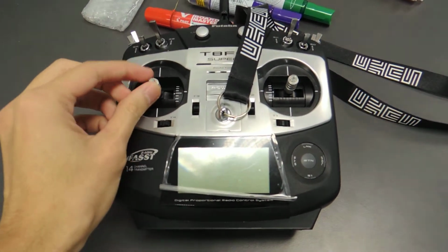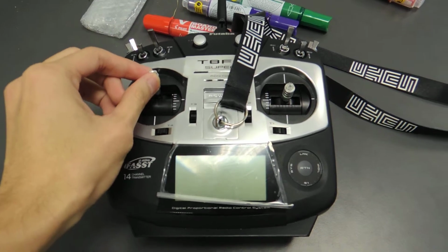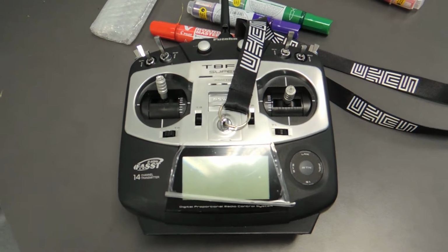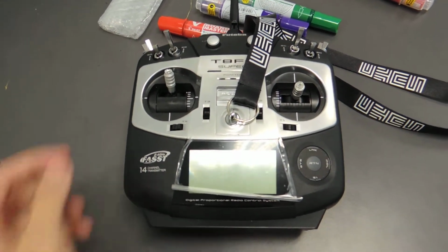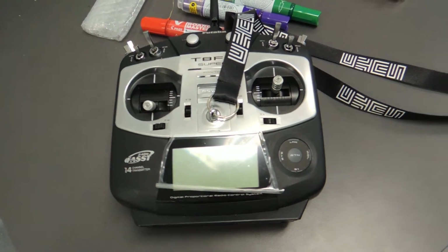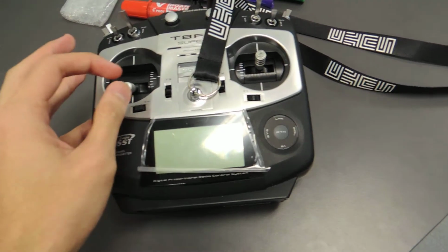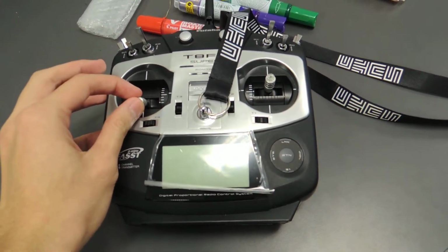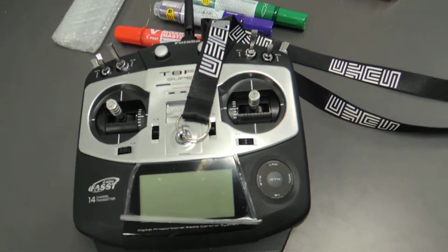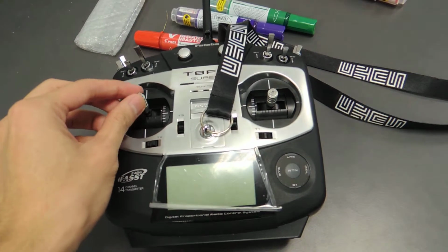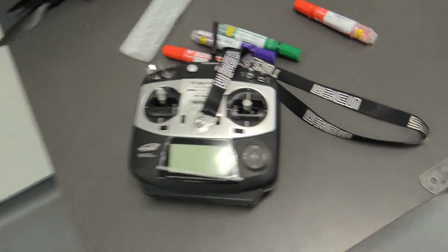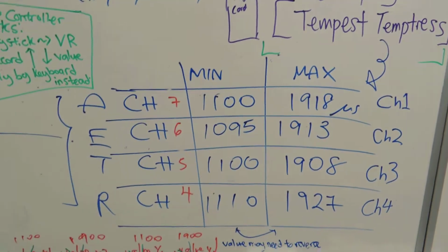When you are powering up using a controller, for example, you are giving a signal of sending full throttle. It gives a certain value to the flight controller on board. And when you are pushing it down all the way, you give another signal of a different value. That's what happens when you are trying to control a flight machine, for example, a quad-rotor. And if I were to power it to an intermediate step, it will give a different value. So when you place the throttle at different places, it will give you different values. This is how you control a flight controller on board and eventually control a motor.